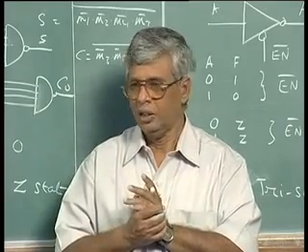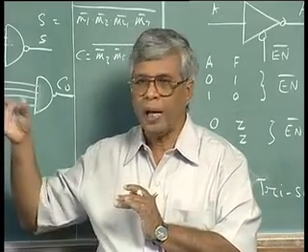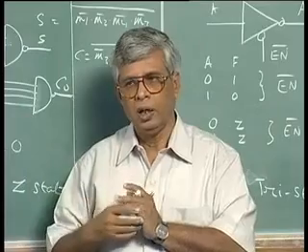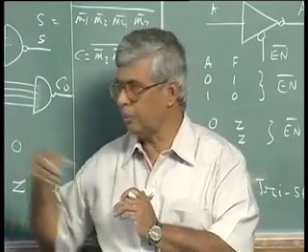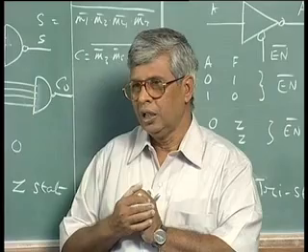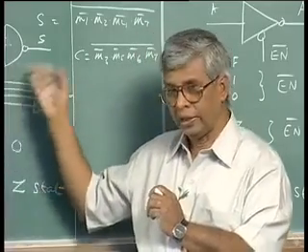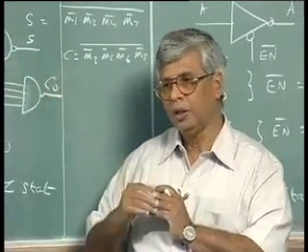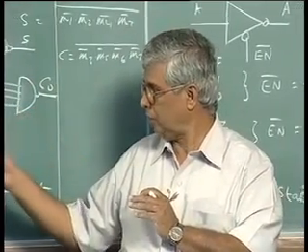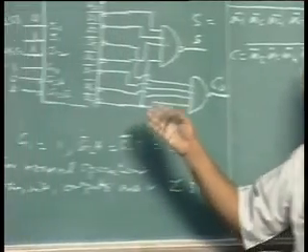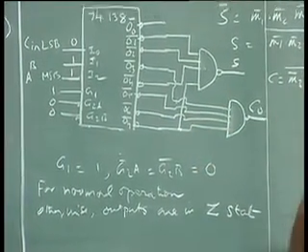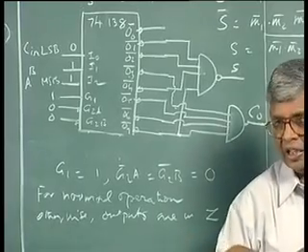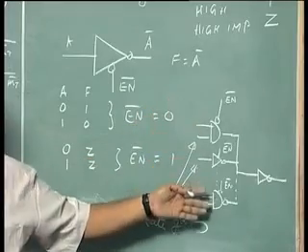Then we talked about mux and decoder, which are two major components in MSI design, and we talked about how to map a given Karnaugh map into this hardware. We talked about the enable feature and how active low and active high outputs are possible, and how enable features control the operation. What happens when the circuit is disabled? It goes into high impedance state, or high Z state, and this is the idea behind that.